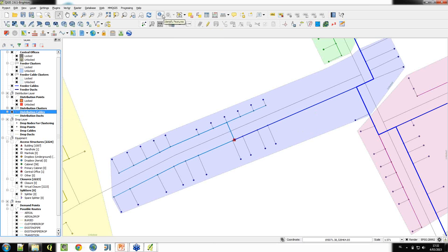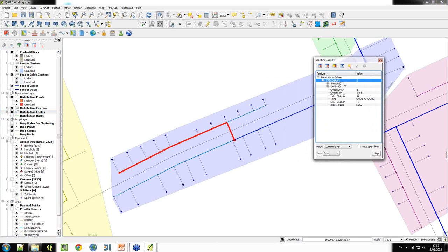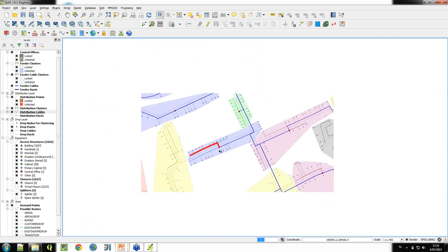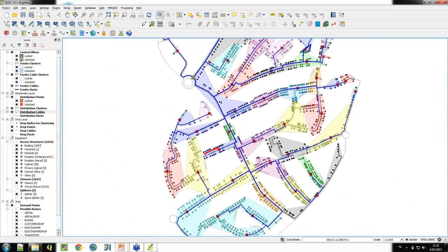And let me show you, each demand point gets a single cable from the distribution point running here. So this is a single 2-fiber cable running from this drop point to the distribution point. And this is the case for each cable. So here we have a cable running in the same trench as this other cable for serving this demand point. All of these cables are running back to our distribution point, and from the distribution point, cables are running back to our central office location.